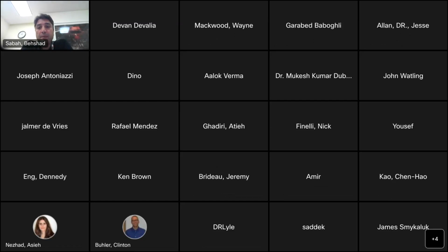The first one comes from Ken and says, of the 1/3 that failed by fatigue, what percentage are from subsurface crack initiation? That's a good question. I do not know the statistics offhand, but I dare say that surface initiated, so lubrication, because anything related to lubrication we see the most. Surface initiated fatigue is closely related to lubrication issues. So there's a much larger portion of fatigue related failures that would be classed as surface initiated.